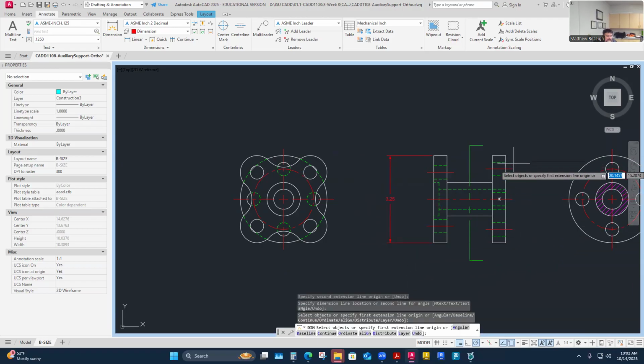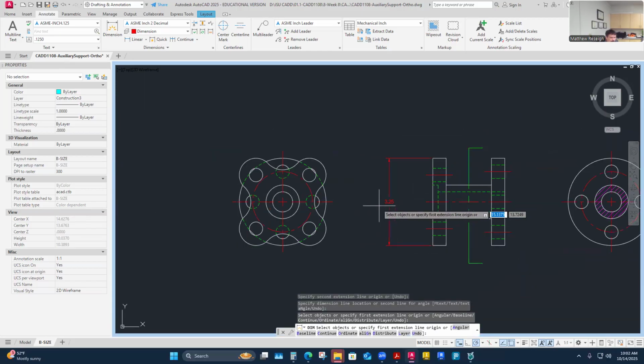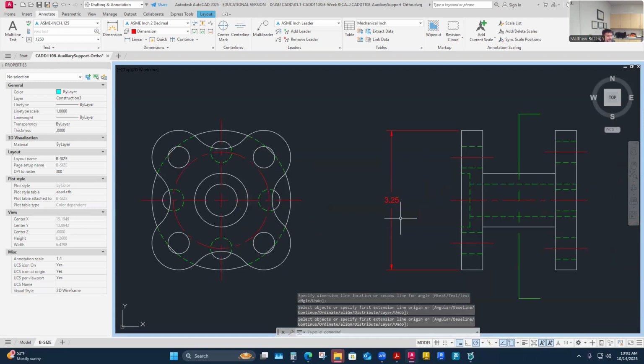If I pull this other one, I'm definitely going to put a diameter associated with it because it is kind of off that round plate. If I pull this one, it's less like a diameter and more like a linear dimension. So I don't have to put a diameter on this one, but if I did pull it off this side, I would. Just remember, watch your diameters when you're pulling off something that's round. Add a diameter even to the linear measurement. I think I'll leave this as my overall height, though.